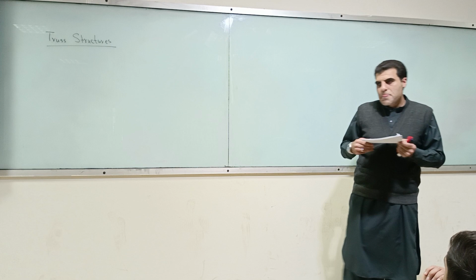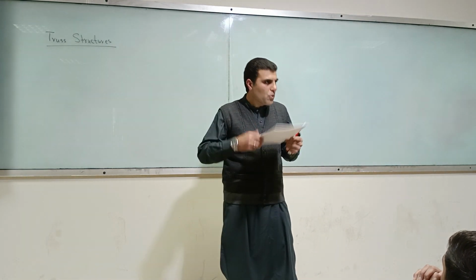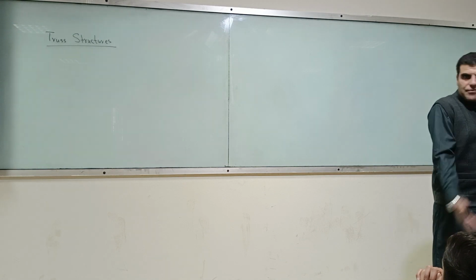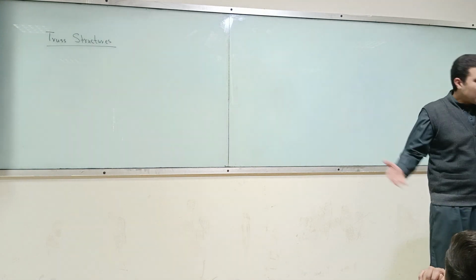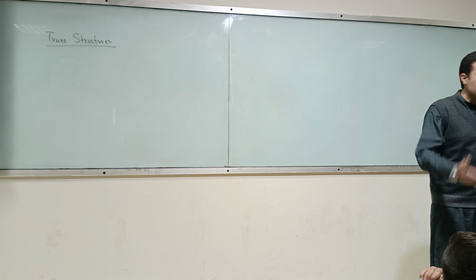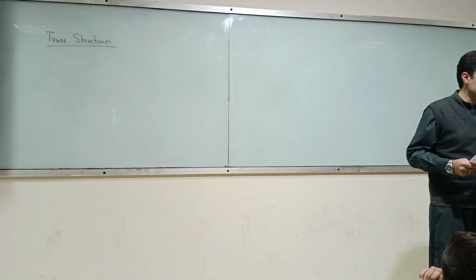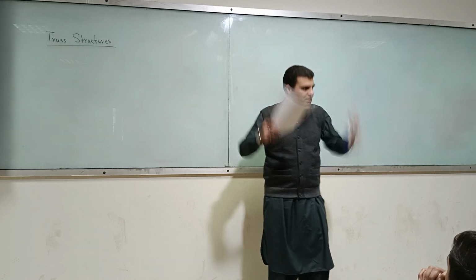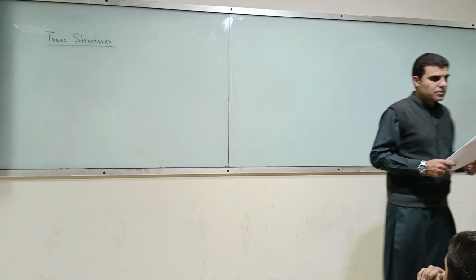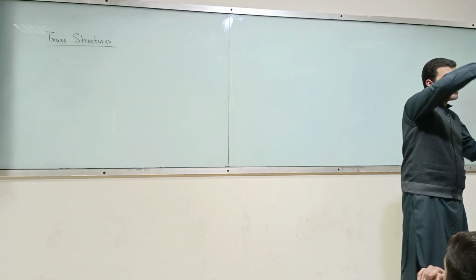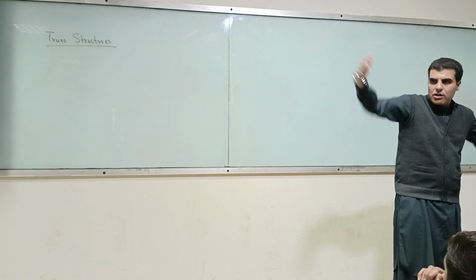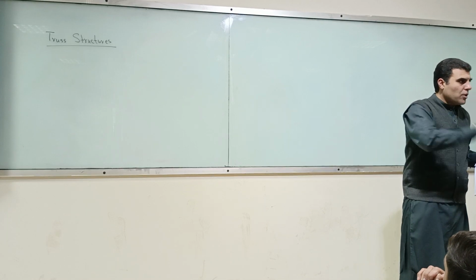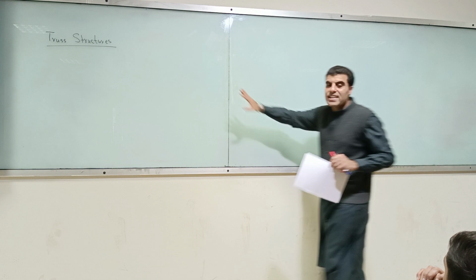But there is a point beyond which it's not able to sustain its own load. Because if I make it too thick, that becomes too expensive, and it's not able to take its own load. It collapses under its own load. If I keep on making it thicker and thicker and longer and longer, a stage will come that I won't be able to do that. Therefore we go for structures like trusses.